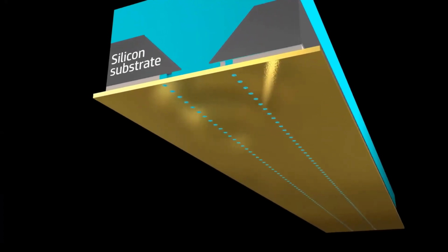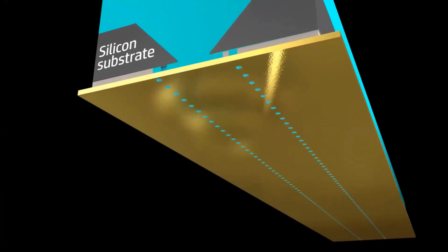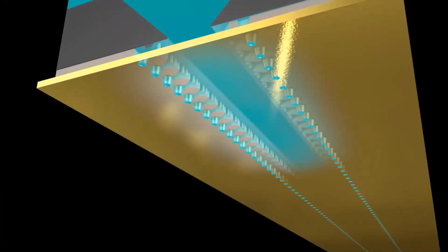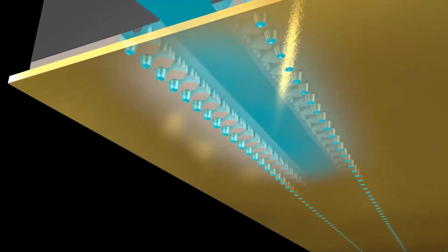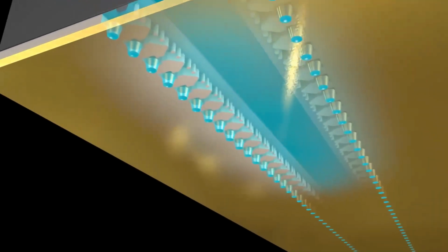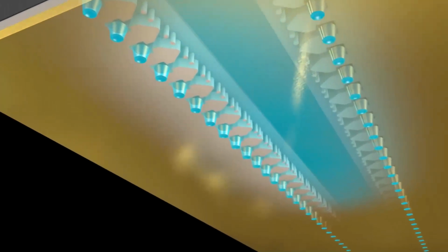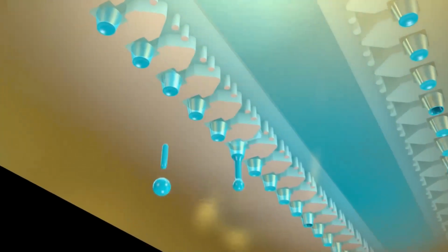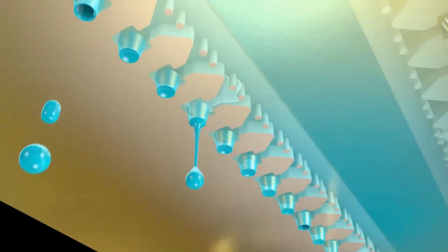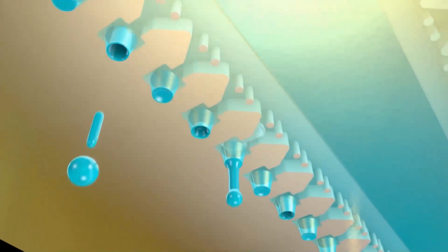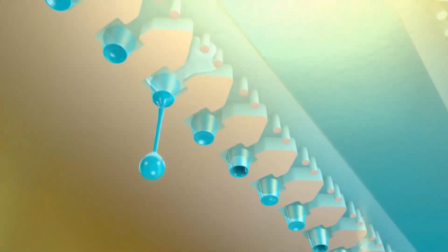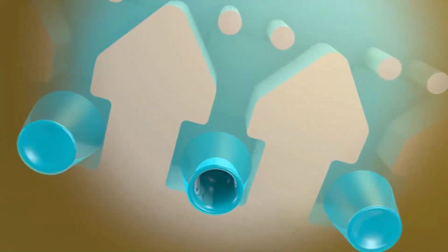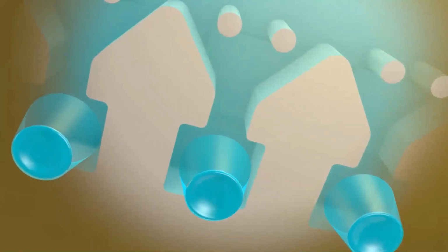The printhead's electronic and fluidic components are built on a silicon substrate, shown in gray. HP builds thousands of identical nozzles and chambers on each die. A high-resolution optical process used with light-sensitive polymers produces features with integrated circuit precision. When generating drops, the nozzles in the 2 columns fire in a sequence that minimizes fluidic interference. Let's take a closer look at a drop generator. So you can see inside, we've made the nozzle plate and cyan ink transparent.